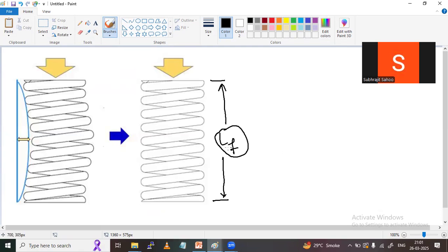What will happen if the coil diameter is fixed at D, but the company manufactures a very large free length LF? If a little amount of load is applied, then the spring will bend like this. Why? Because here LF is very much greater than D. That means there should be a relation between LF and D so that this buckling effect will be minimized, and will completely disappear.